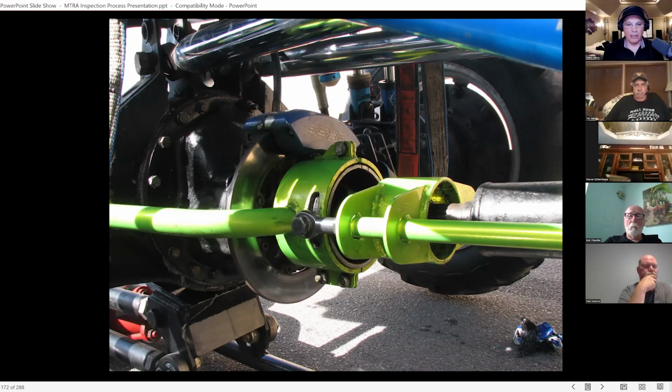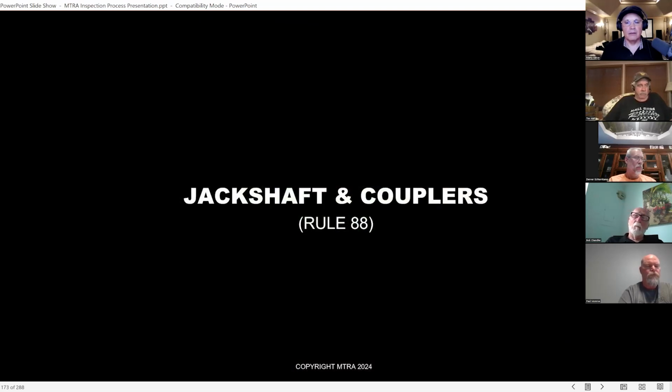What that allows is that since the axles can articulate, and one end of the loop is affixed to the chassis, which is solid. It depends on what end; by our rules a rotator can be on either end. But what that allows is that the axle can pivot from side to side without trying to twist the loops. It allows the loops to stay parallel to the chassis and allow the axle to twist without twisting the loops. And it makes a huge difference.